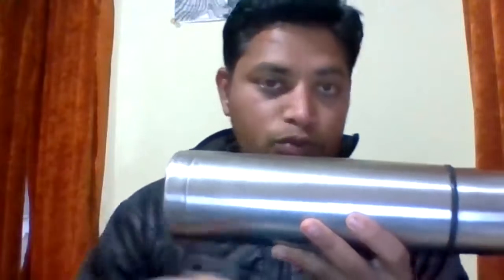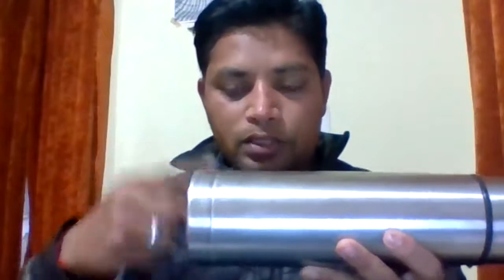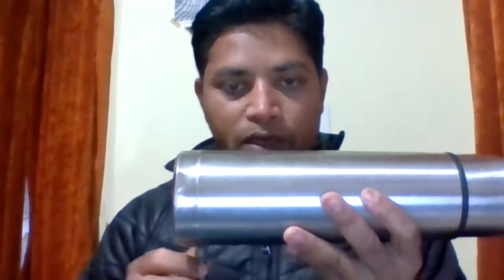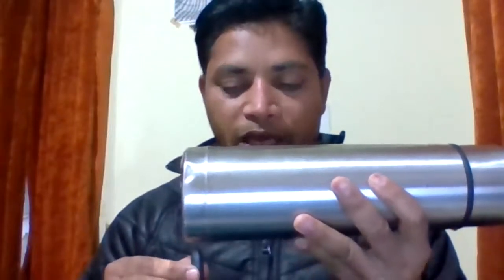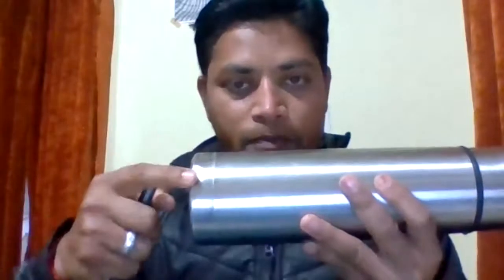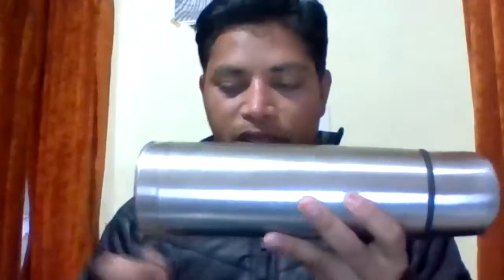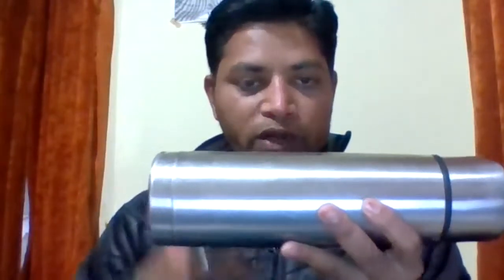Now again we give the 0.5 mm depth of cut and move in this direction. So what is happening is the material is removed along this generatrix. Now we are giving the feed. First we remove the material from this periphery, then the tool moves here, removes the material, then we shift in this direction. Now the material is removed from this area. So this is the generatrix, and perpendicular to that is the directrix. Okay, simply we are talking about this one as well.